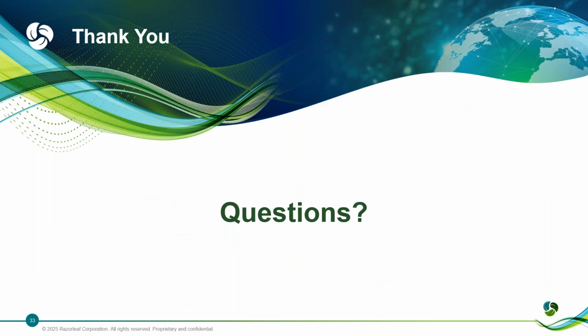All right, well, thank you, Kip, for that very informative presentation. We have a few questions here. The first one, is it possible to filter the eBOM without using the product architect role? It is. It's a little bit more difficult. It takes a few more steps, but you can actually create filters in the engineering definition or the XEN application based on selections. So you could create a filter and then select which items belong to that filter. So it's not as effective, but it is possible to do without the PAU or the product architect role.